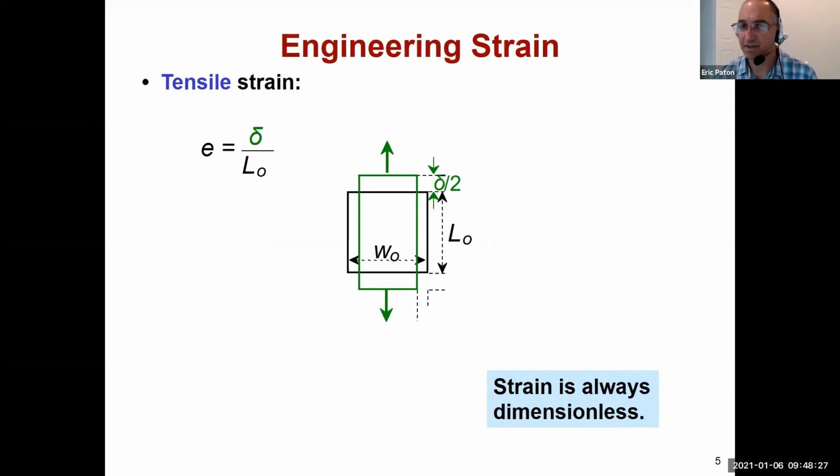The other one is called strain, and engineering strain is when you divide by the original length. Okay, that's engineering strain, and so it's the change in length over the original length, and this is epsilon. This is the strain, and it's a unitless dimension. But since volume is conserved, if we have an increase in length, we're going to have a resultant decrease in the width as we pull on this. And so, who can tell me what that ratio is called that defines the amount of change in length relative to the amount of change in width of the sample?